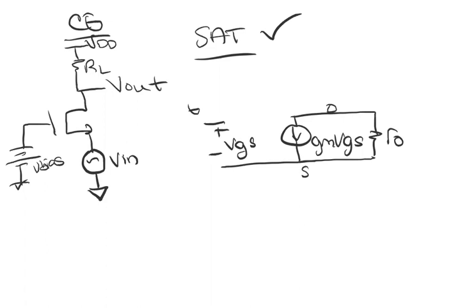The gate of the device is V bias in the schematic, which is AC ground. Let's check, does that make sense? Yes, because this is a common gate, meaning the gate should be AC ground. My source is where my input signal goes, and this is a small signal input, so it remains in the small signal model as VN going to the source.